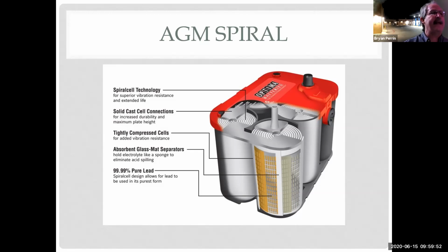So you think, why do people use them? Well, first of all, my regular lead acid battery has water or liquid electrolyte in it. So if it falls over or splashes, acid goes everywhere. This, I can mount it on its side. It doesn't leak and it still works. I can put a lot of power in here. So these have some applications that they work excellent in. But the car you're driving every day that you want to have the battery last for 5 years is not one of them.